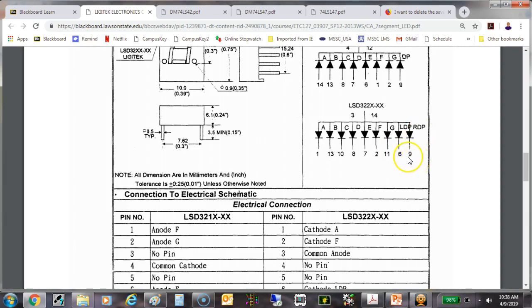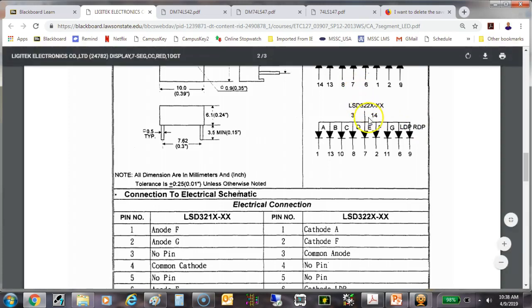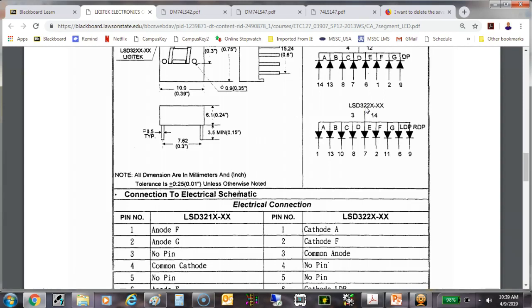So what you need to do now is go ahead and do the pin out on page 96, figure 13-3. You need to do the pin out on that, okay? So you notice we're missing pin 4 and pin 5. We do have a pin 3. We're going to use pin 14, even though I could have used pin 3 to power up the anodes. We've got a resistor up here because all we're going to be doing is turning on one segment at a time. What I might do is turn on multiple segments, and you'll see how each configuration actually dims out. Okay.